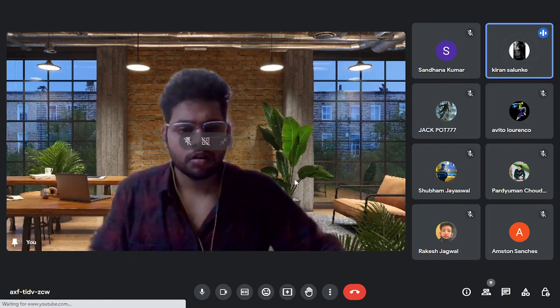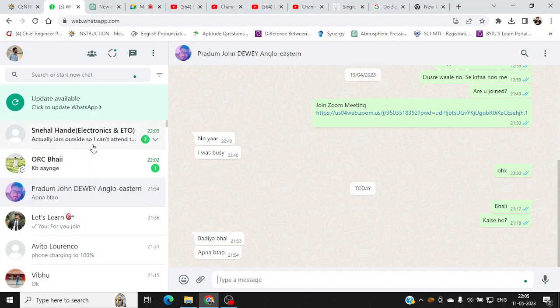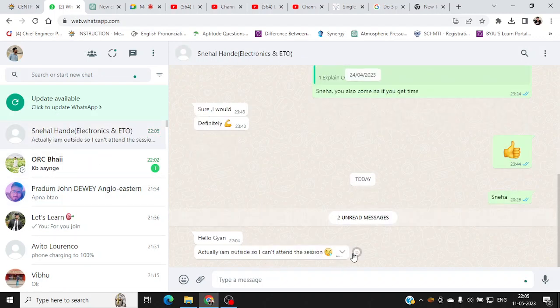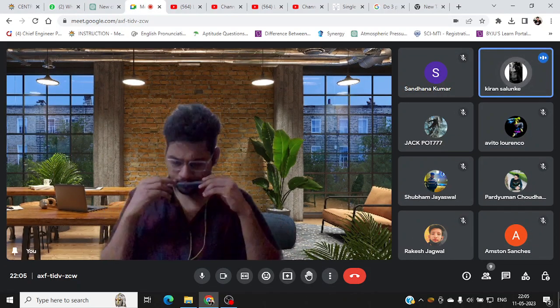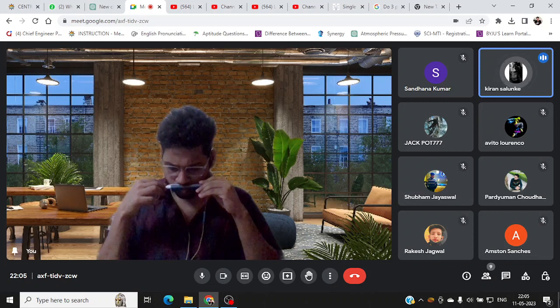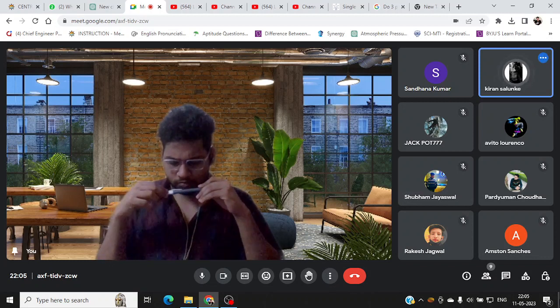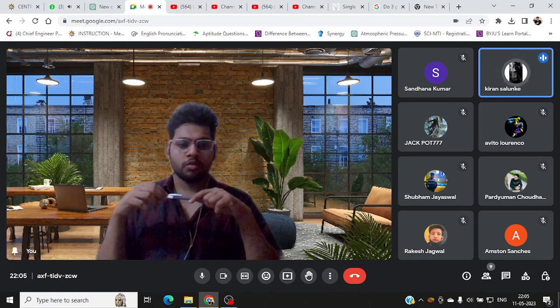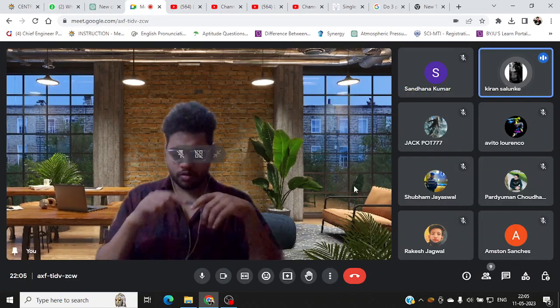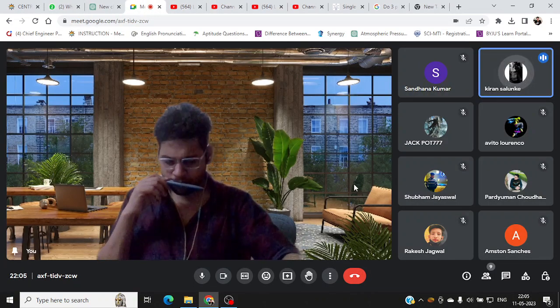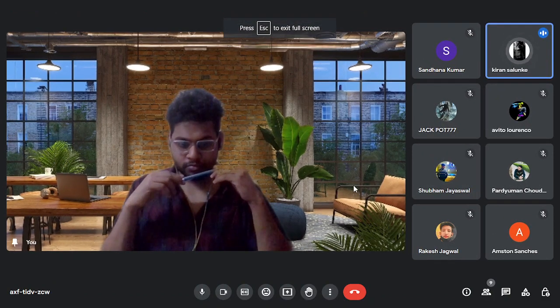An AC generator consists of a magnet which creates a magnetic field and an armature coil which rotates inside the magnetic field by means of mechanical energy. When the coil rotates inside the magnetic field, the magnetic flux changes. Due to this, EMF is induced in the conducting coil. As the coil is a closed circuit, current flows through the coil. As the coil rotates, the direction of EMF and current changes. The changing direction of the electromotive force after every 180 degrees of rotation gives the alternating current.